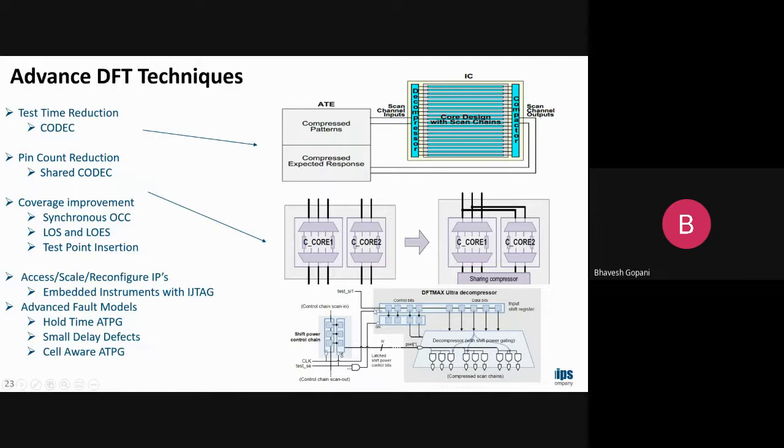This also helps us to use a single pin. Similarly, on the output side, a compactor compacts all the chains, the output goes to the deserializer, and the deserializer output goes to the final SO scan out. So this is one of the techniques I tried recently.